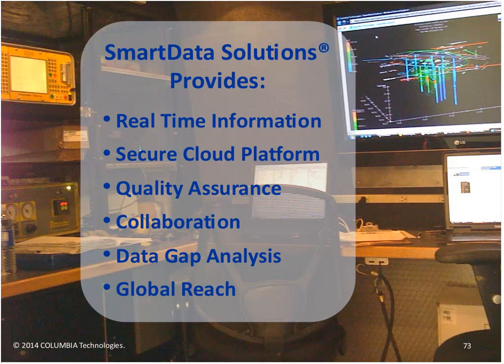So you can pretty quickly, off the platform, zero in on what depth strata is of concern, what's the extent of the contamination, what depth zones they are working in, and how my laboratory monitoring well or sampling information compares to my direct sensing information. So really, again, just trying to speed up this whole information flow of what's going on.